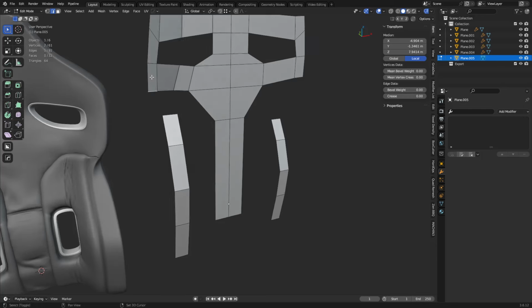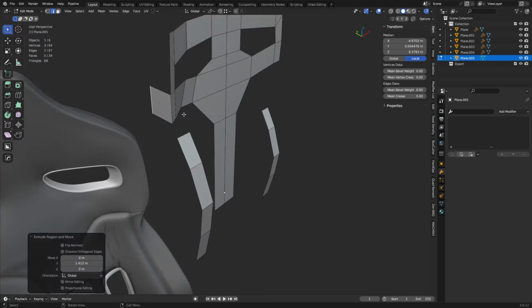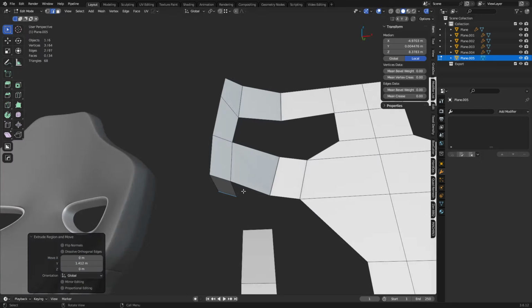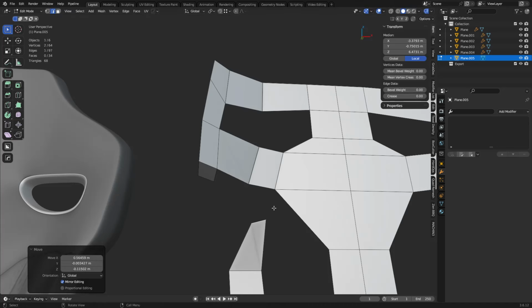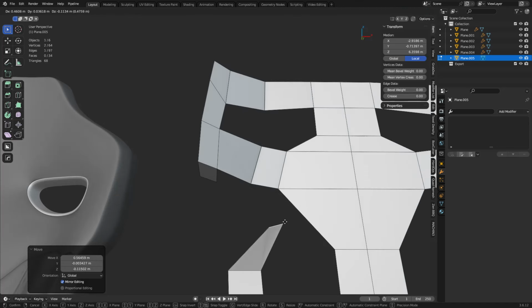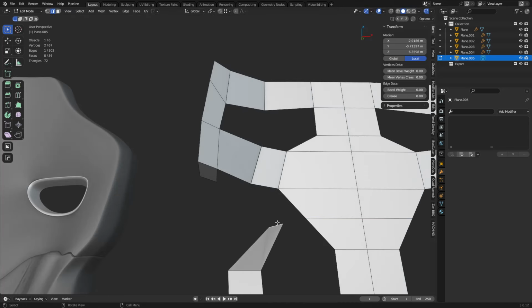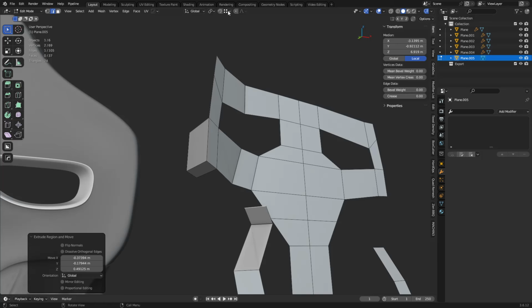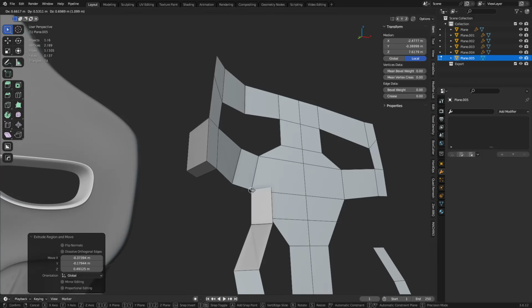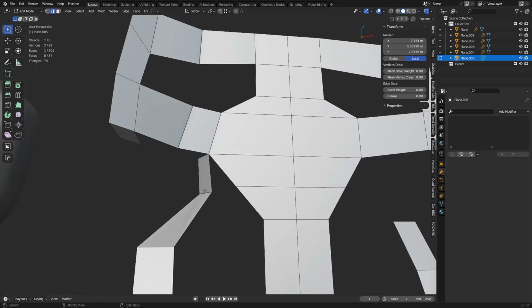So at some point this comes all the way out and it starts to become thick. You can wait to do thicknesses later usually, but this one's going to start to rotate, you see? And it's going to go into somewhere down here, like right here almost. It's going to start going this way. And you want to use vertex snapping too, so you can just snap things if needed. It gets a little bit squirrely sometimes, but it's still useful.